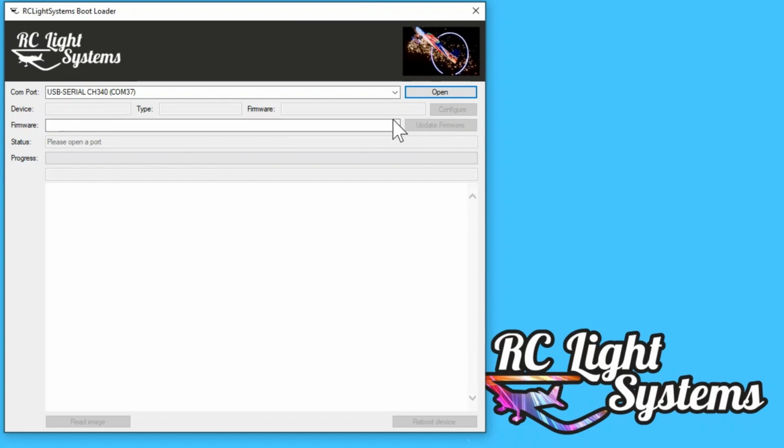If you do update firmware, there is a chance, depending on the particular version and how it's been configured, that that firmware may overwrite the settings that you've got. So you should always make sure just configure and save and come out, and that's it. Only click the update firmware if you really want to update the firmware. This can change your settings, so just be aware of that.